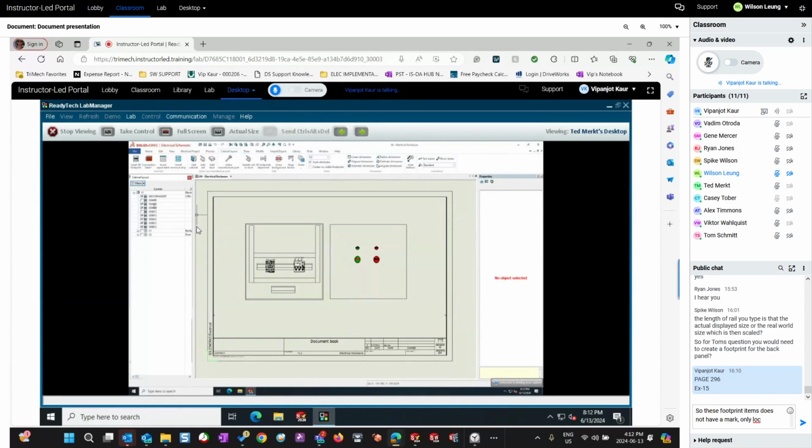Very good. So now in step number 2, they're saying anything that has a checkbox on is already inserted, and they want you to insert 036612. Right click on this, insert, and this is a duct. So you can click insert a duct. Click. So now click and drop it here on the top. Very good. So one click. Now the second click is for resizing it. Do the second click on the very right. Yeah, click. Good job. So you dropped a duct. So see the check mark has come on now, Ted.